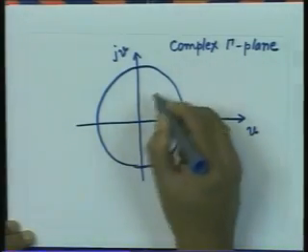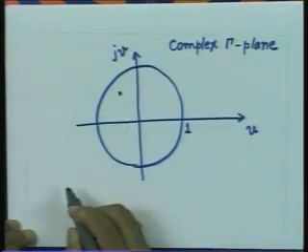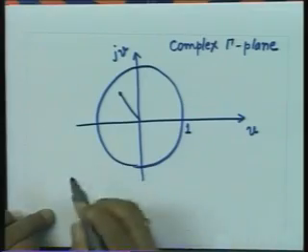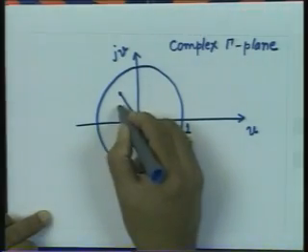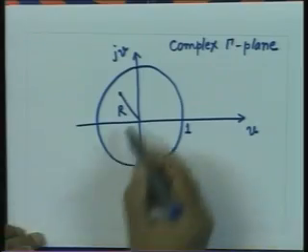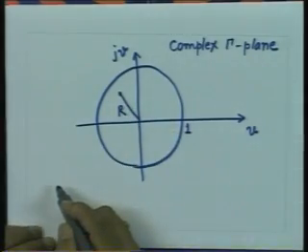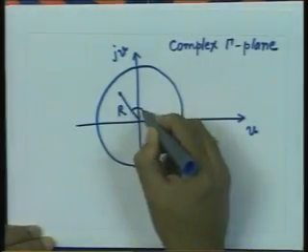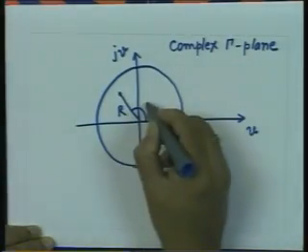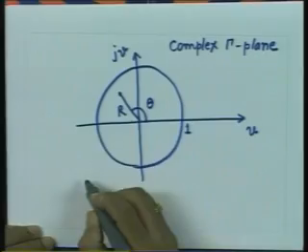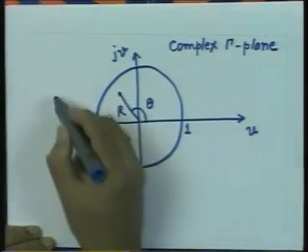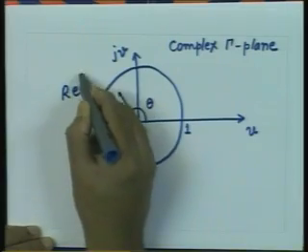So, a reflection coefficient point here has a magnitude as we mentioned. If I represent that in the polar form, this distance from the center of the complex gamma plane gives you the magnitude of the reflection coefficient, and the angle of this vector from the real u axis gives you the angle theta. So, this point is the complex reflection coefficient point denoted by r e to the power j theta.